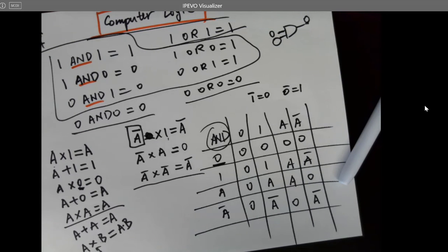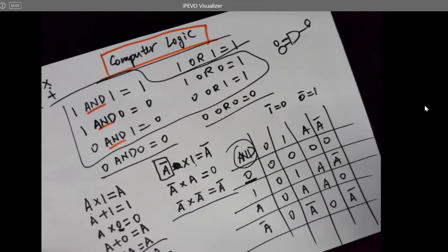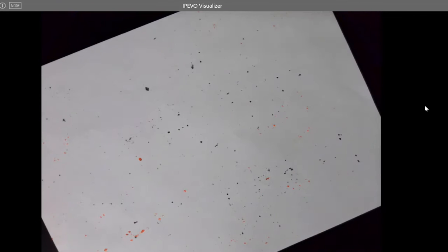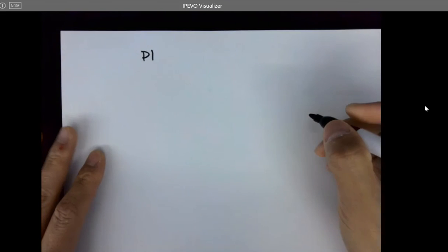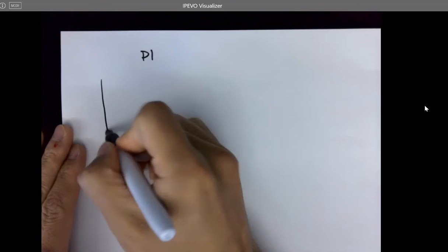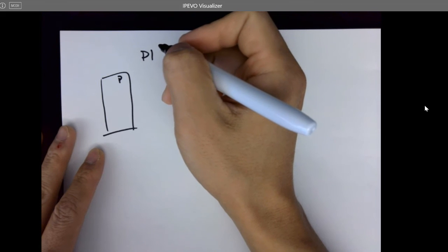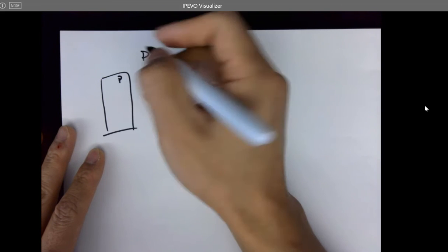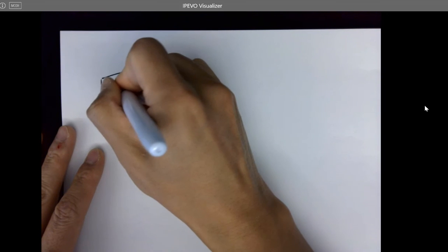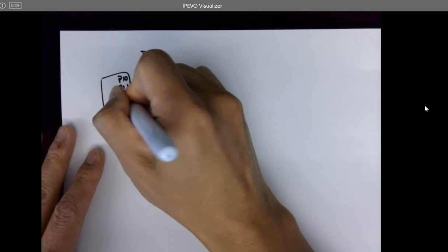But when you're trying to debug it, you have to look at what they write down, for example, page 4. For example, there's a pin like P1, pin 1. P1 has 8 digital pins for the chip, starting from P10, P11, P12 until P17.